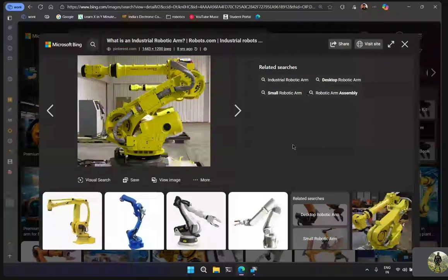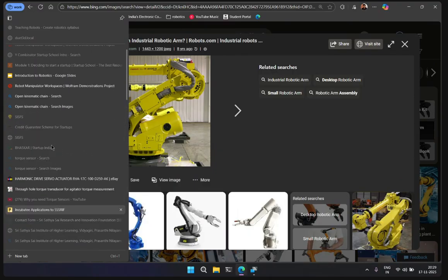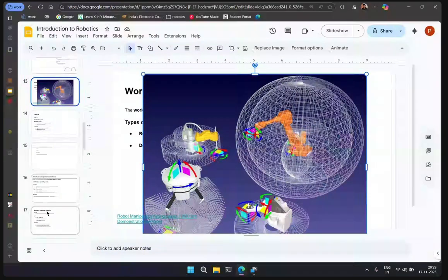To rotate it, we have different gear systems. Gearboxes, like either a worm gear system or a planetary gear system. When so many parts are moving, there will be an efficiency loss, so we need to consider those. Here we have gearbox one, two, three, mostly first, second, third as gearboxes, and these ones have belt drives. So that is something we have to consider while planning a robot arm.